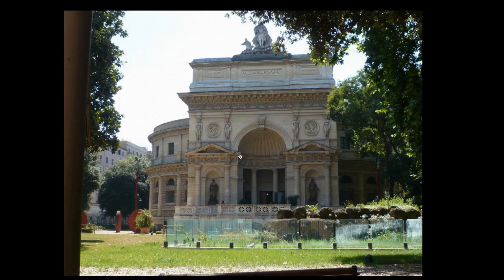So that means when you design that, you first need to find the height of the main column, probably a composite or Corinthian column, proportion 1-to-10. Then they take the column away and leave the height of the entablature, which should be around 25% of this. If this is 10, then this is usually 2.5 column diameters. So here column diameter, here 2.5. This gives this massive entablature. Then you fit in the arc.